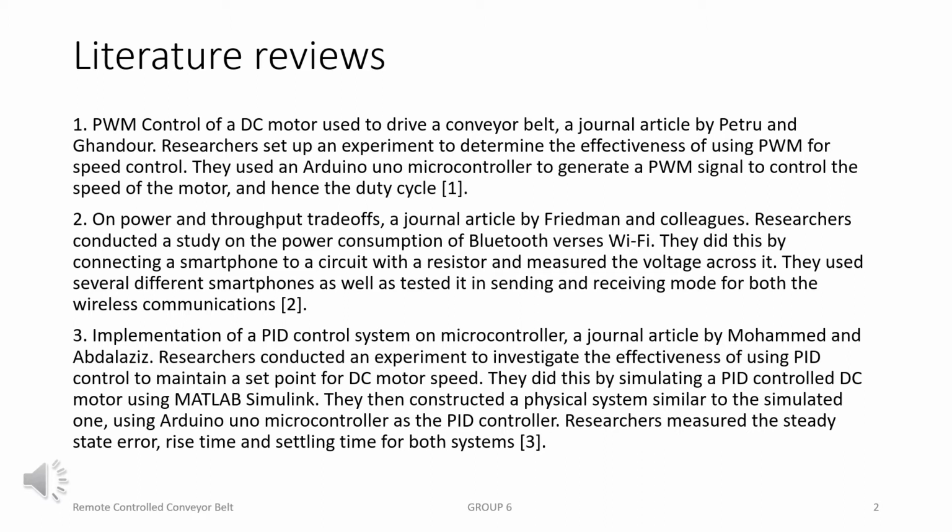They found that the data transfer rate was much higher for Wi-Fi. However, this resulted in a power consumption almost 2 to 3 times that of Bluetooth. Hence, Bluetooth was seen as favorable for our application.